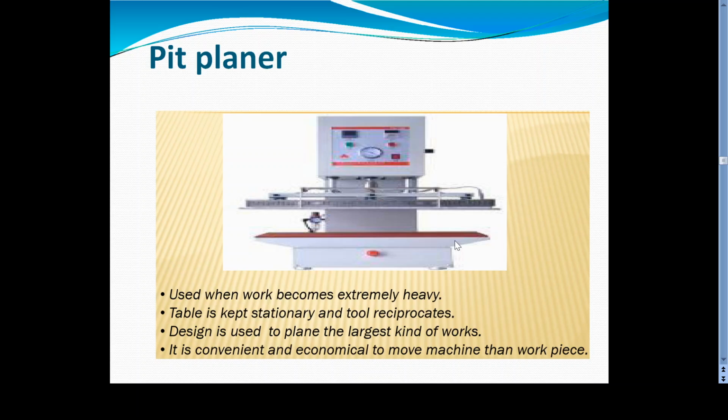Pit planer. The pit planer is entirely different from this double housing or cantilever type planer machine, because here the tool head is moving, not the table. So the table is kept stationary and the tool is reciprocating.